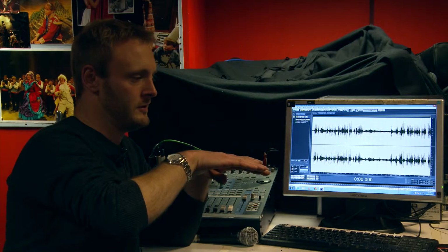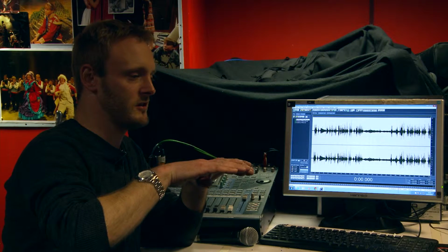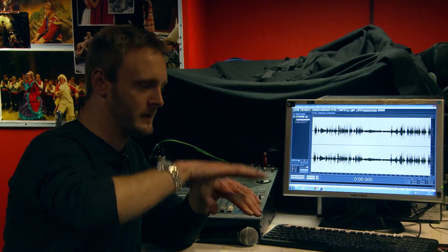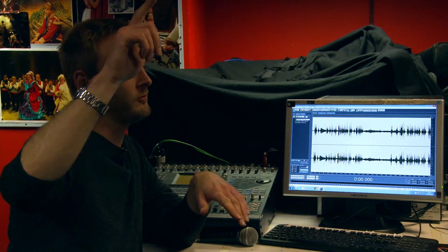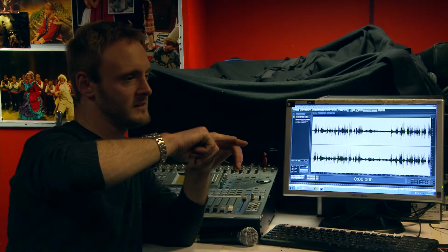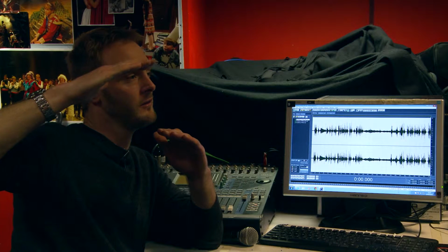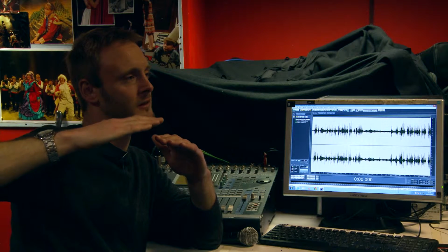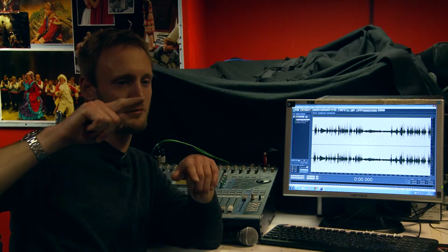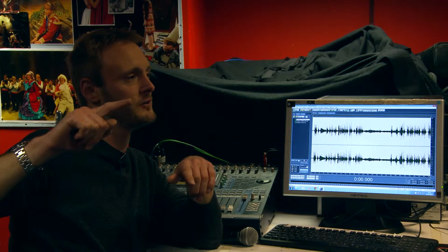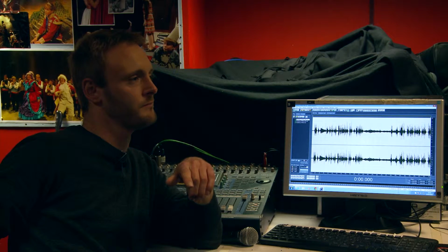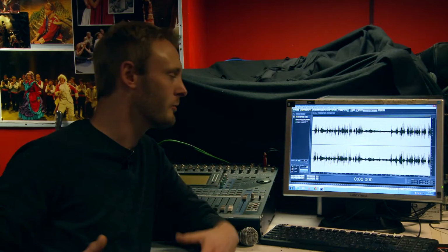So you've got silence, silence, silence, you slam the snare drum, bang, it goes off the scale too loud, but as the voltage increases, the voltage-controlled amplifier is pulling the volume down, so it never actually reaches the summit. Before it hits the top of the dynamic range, it's back on its way down again. Okay? Really simple little concept.